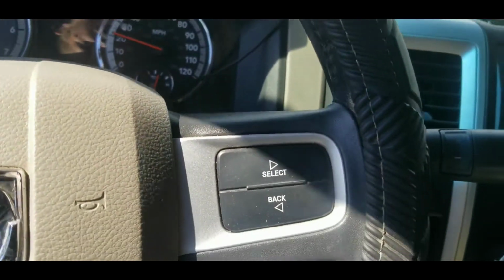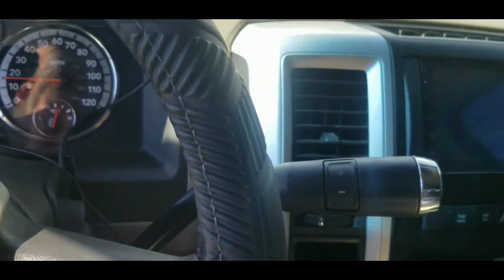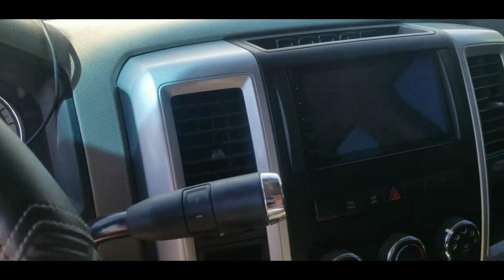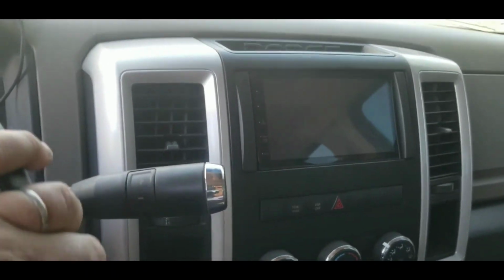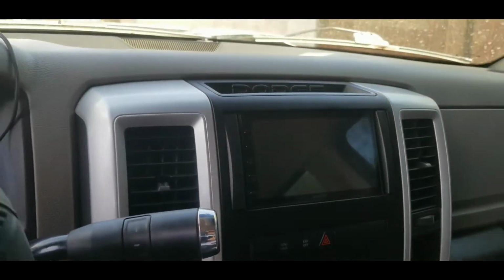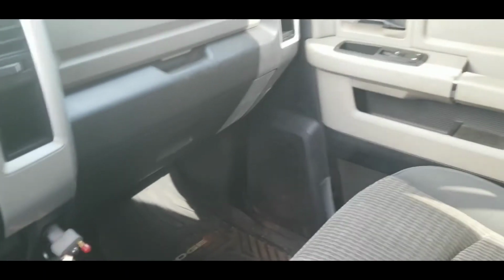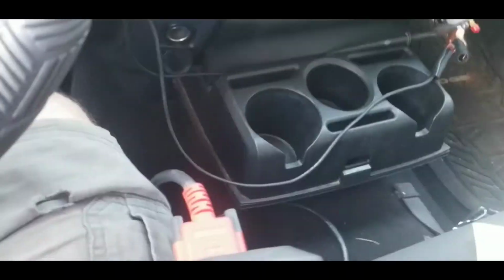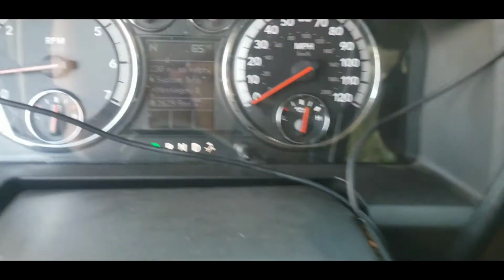That's kind of getting scary, like maybe we're starting to really have line pressure issues really bad. But neither one should be on at the same time, and then the other one comes on for a split second, and as soon as that happens, you barely catch it with the scanner. It's barely long enough for the sample rate on the scanner to pick it up. I think we got it. So look, there's not even a check engine light.